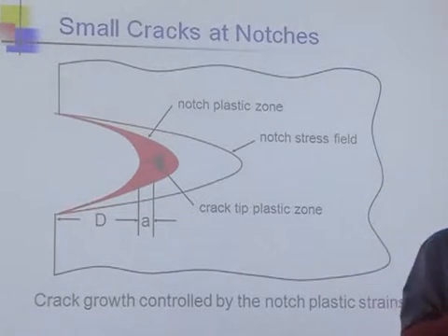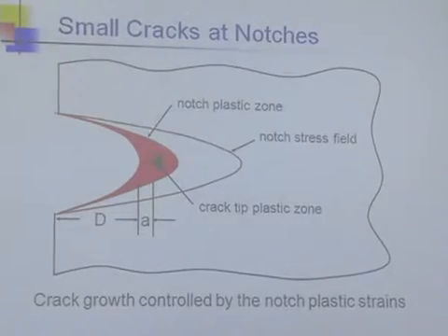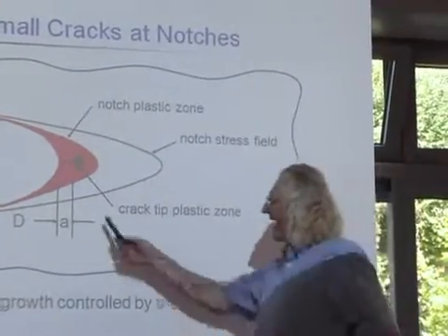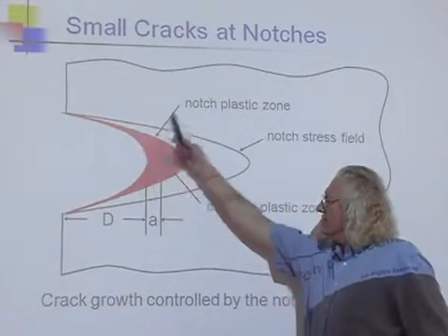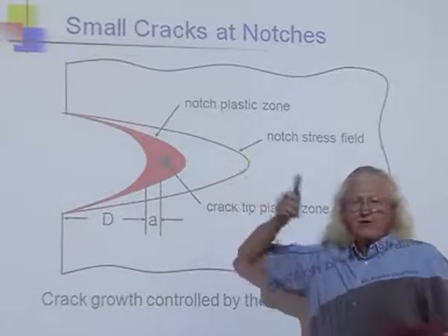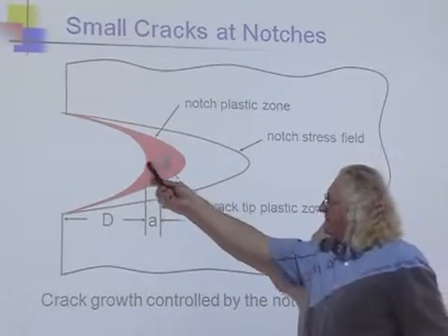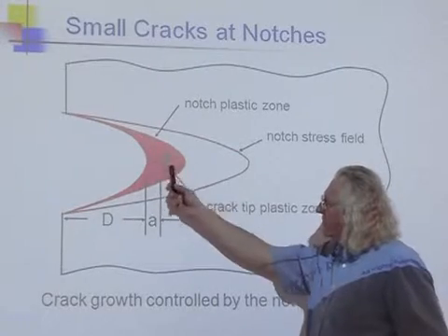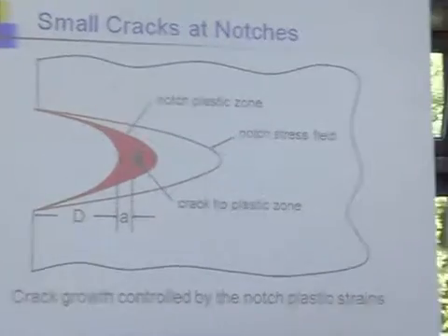What you see in this picture is that the plasticity driving the problem comes not from the crack, but from the geometry, the geometrical notch, and of course the nominal stress. And this is always the second stage of fatigue. The second stage of fatigue is I nucleated a crack and it's now going to grow in some plastic field. So let's look at how that happens.